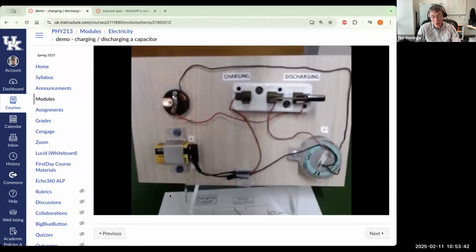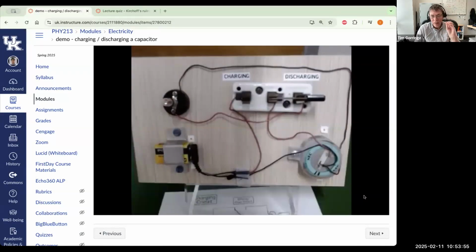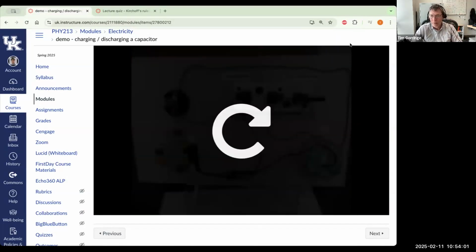Now we're watching the light bulb with less and less current flowing, less and less charge on the capacitor. Maybe this is 2 time constants, and so on. And by the end of the video, maybe we don't see the light bulb at all. It's vanished to almost nothing. That's probably 3 or more time constants. That's a longer answer to that question than you probably wanted. Any more questions?